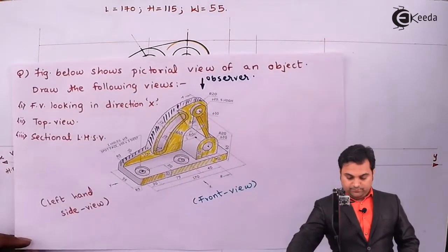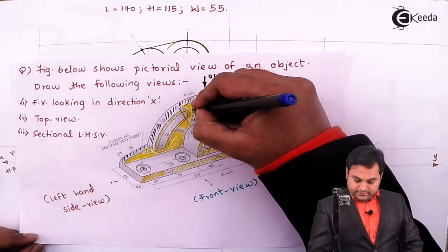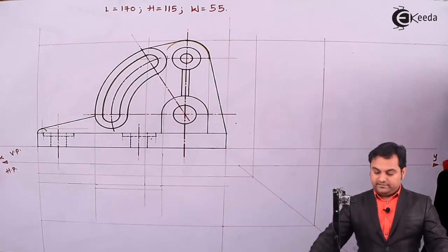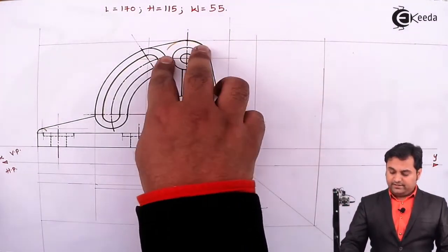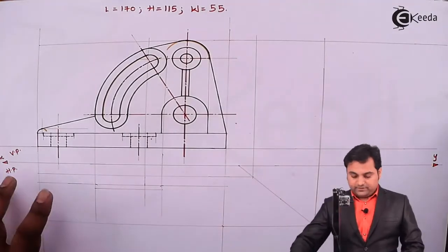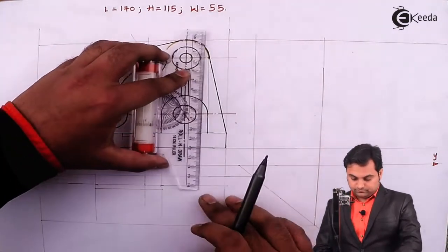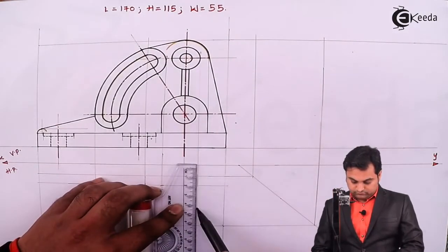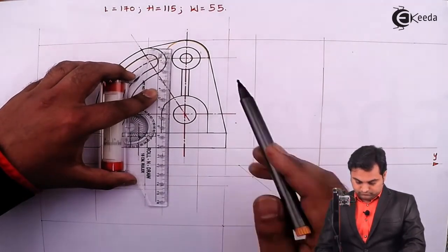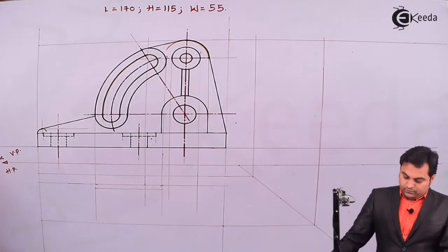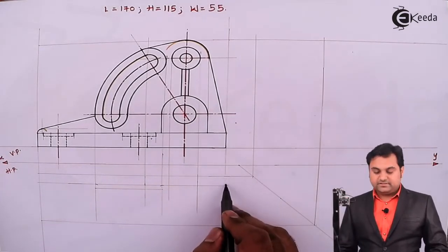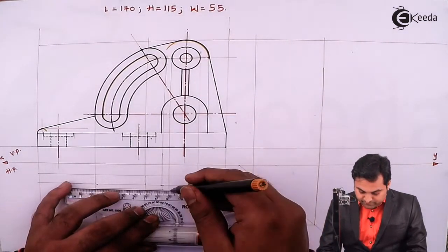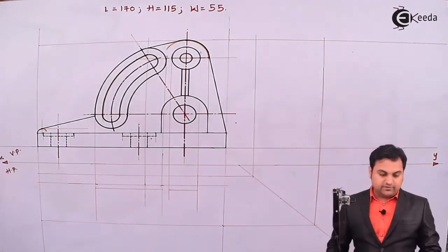After that, looking from top, even this circular plate having a width of 5 mm will be visible. So its length I'll get from the front view, and the width is 5 mm. And that portion is starting after this 10 mm width plate. So taking 5 mm will give me that circle or the circular surface visible from top.